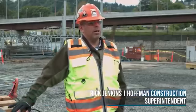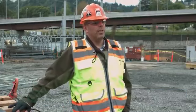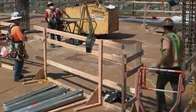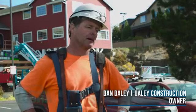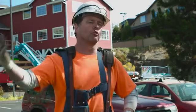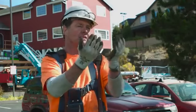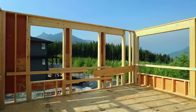When I run projects and set up activities to happen on a construction site, I will always try to be in fall protection. Top rail, mid rail, toe board, and naturally you on the common sense side of that assembly, because it essentially eliminates fall arrest. Usually we use them around holes in the floor system. Like if the perimeter, when we're building a second floor system on a building, we'll be tied off wearing our fall protection till we have the perimeter wall stood. And then once that's stood, all you've got to do is put your rails through the window holes, and then you can't fall.